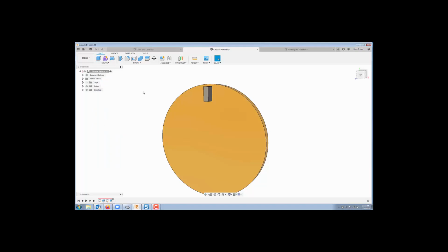The other is, as many of you follow me, I go to the S key and I bring up my toolbox. I happen to have these located right here, but if I did not, I can just type in a hint, like I'll say circ, even just start spelling the first couple letters, and you're going to be offered a number of choices. So right here, circular pattern, you're going to see there's a lot of other choices up here, and each of those choices to the right have a little up arrow, and that just means I can add this to my toolbox. If I go to circular pattern, it offers an X because it realizes that I already have it.